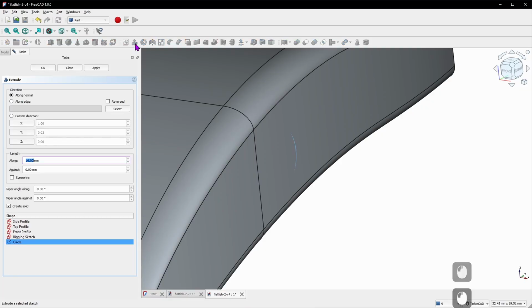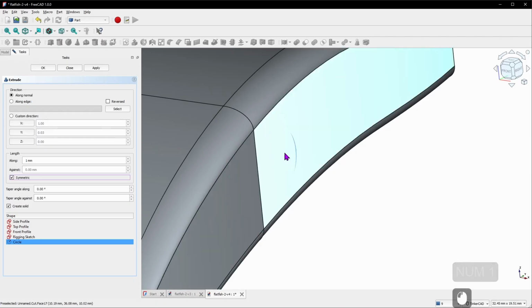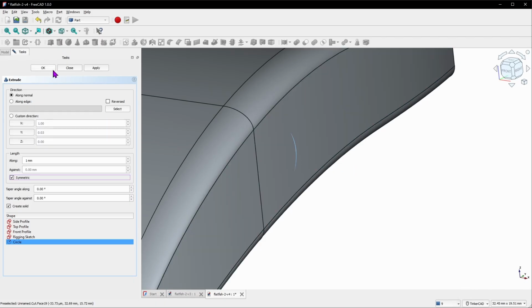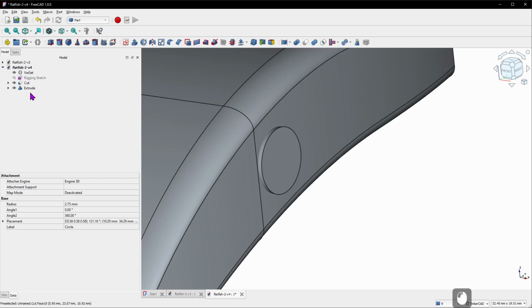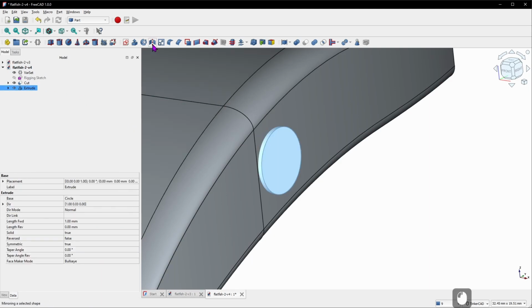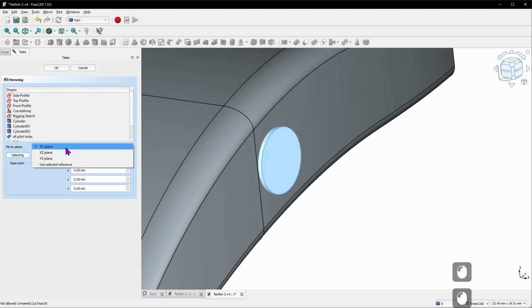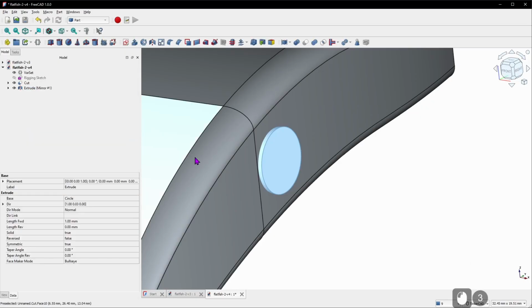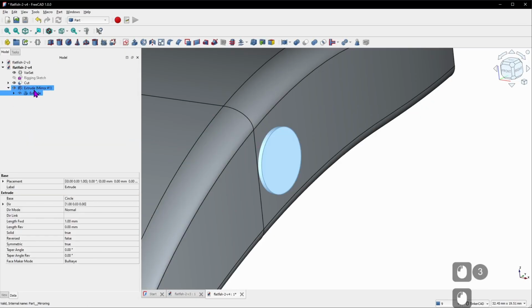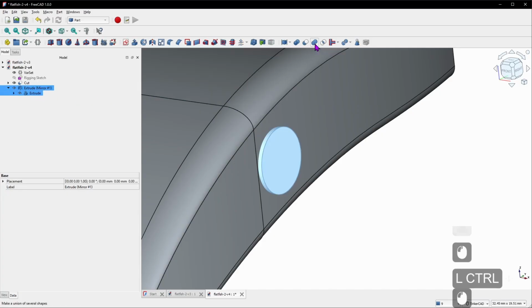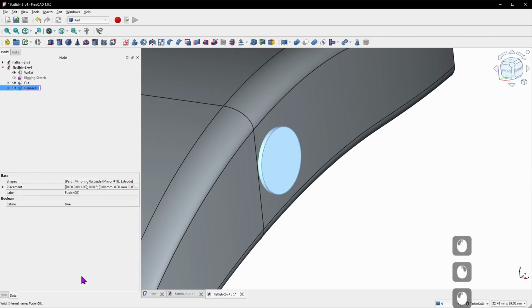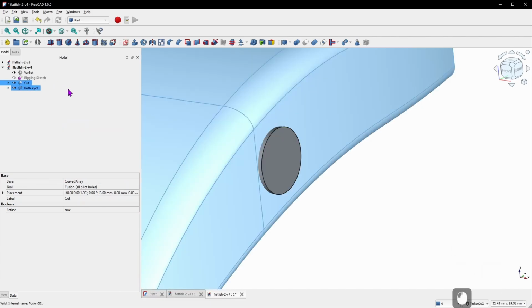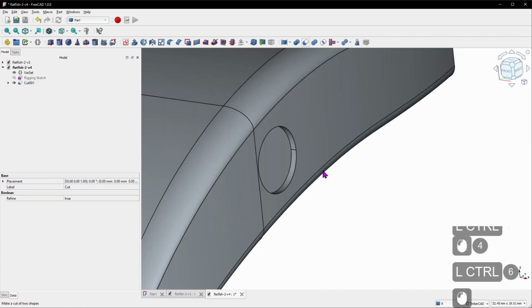And let's extrude that circle. We will choose 1 millimeter symmetric so that we have a 0.5 millimeter hole. And we cut through the outside of the bait cleanly. Let's take that extrude. Let's mirror it along the YZ plane, because that's our side plane. Say OK. Then I'm going to fuse those two extrudes together, or the mirror with its extrude. I'm going to fuse that together, and I'm going to rename this to both eyes.